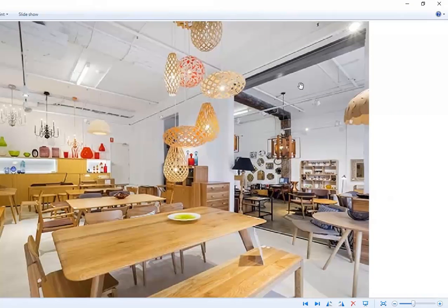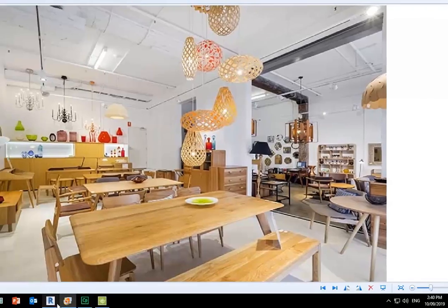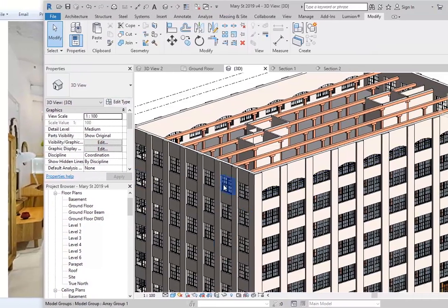Pretty much, yeah. And it's also a technical thing with Revit. If you do line the ceilings, so if you have it like this with some sort of lining, you can use the ceiling tool in Revit and then you can use the ceiling lights in Revit because those ceiling lights will attach to a ceiling. But let's say you want to do the more modern style of design where you leave the surfaces exposed. So you're not going to have a ceiling if the surfaces and the joists are exposed. And so if that's the case, I'm not going to show you the joist, but I will show you the family for the lights because you'll need that.